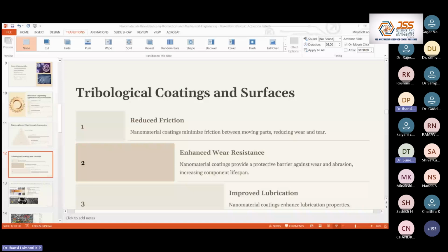Once again, the strength of the coating is checked using scratch analysis. Even after the scratch analysis, failure of the coating is not seen. It is observed that for 20% B4C particles, the variation in traction force is not much, whereas for the other percentages of B4C, the variation of traction force is much more observed.